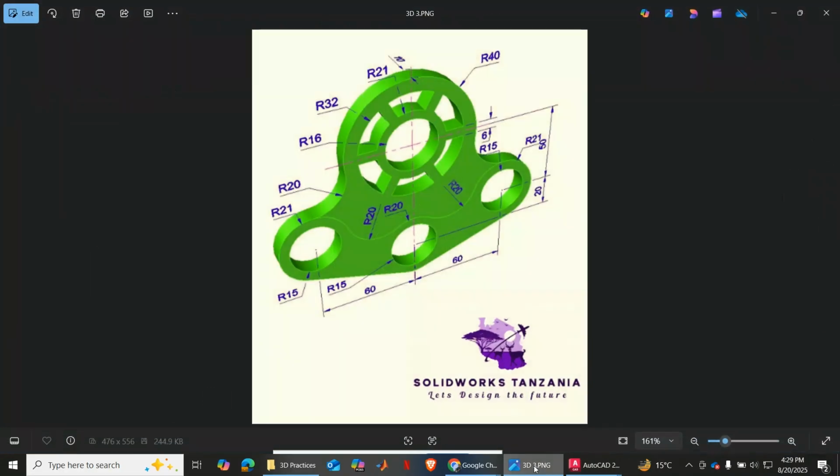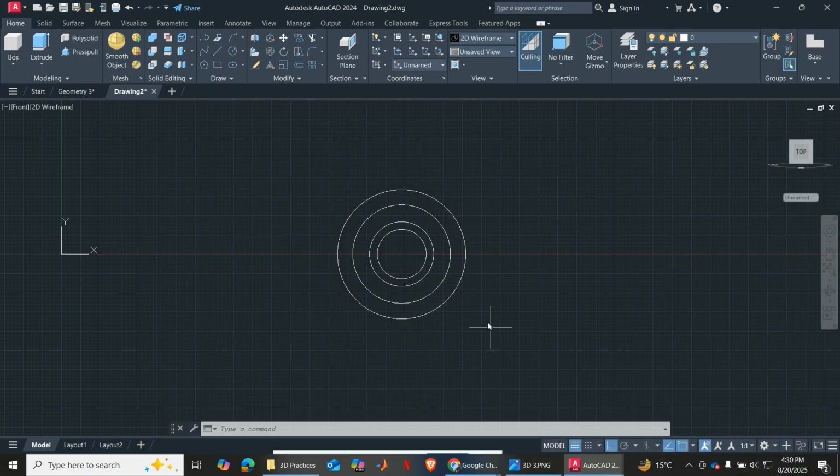And then now I can make this spacing. So this spacing I can draw one here and then array it, polar array, right? Yeah, so there is linear array, polar array. So I can draw this line. This line has a spacing of 6. So that means this is 3 upward, 3 downward. So I can draw a center line and offset it. So it touches here and here, the second circle and the third circle. Right? The second circle and the third circle.